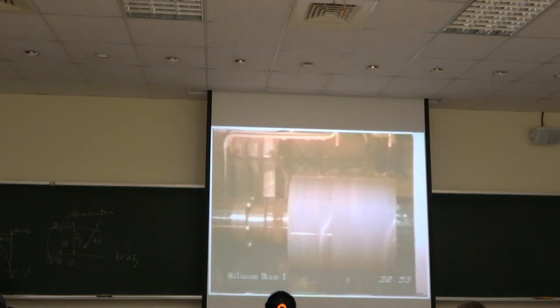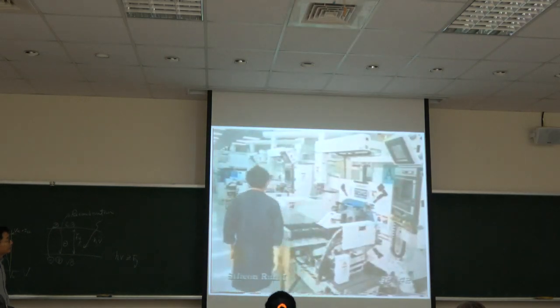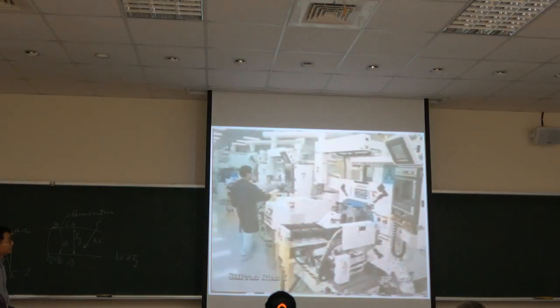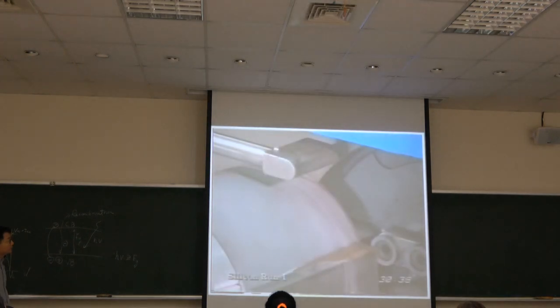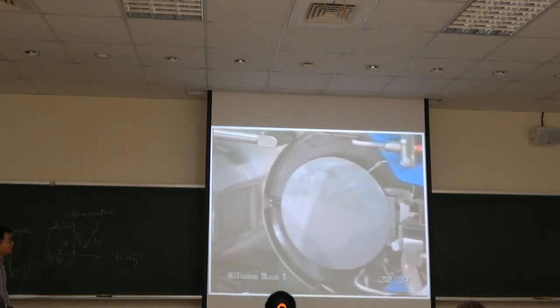The shiny rippled surface of the crystal is ground to form smooth, uniform ingots. A curved diamond-edged blade saws the ingot into wafers that are as thin as possible without being too fragile and difficult to handle.